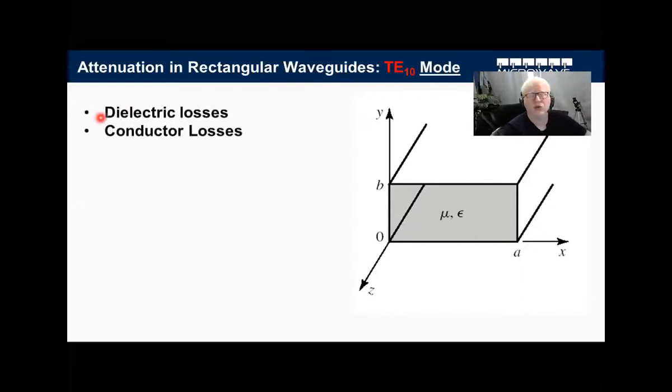Then we turned to the sources of losses, and I told you that we have 2 sources of losses. Either the dielectric losses, which are the losses inside the dielectric material, or the conductor losses, which are the surface current losses due to the conductor. We investigated deeply the power losses due to the conductor. Here, this is the term we will use: J squared over 2. Again, 2 is just the root 2 squared, so root 2 due to the root mean square value. And this is the surface resistance, or what we call the sheet resistance, of the cover.